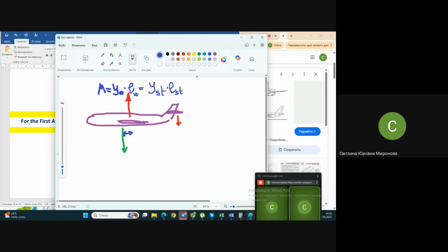And there are three unknown values. What do we really know now? We know only this one, approximately. Not really, but approximately we understand it, yes? And that one is counteracting and stealing the useful lift. That is one more reason why the Zhukovsky formula gave us some value, but that value was too little with respect to the values proven by real airplanes. It was less than necessary. Why? Because we forgot that we have a stabilizer here trying to steal some portion of our lift, and this portion may be rather high actually.